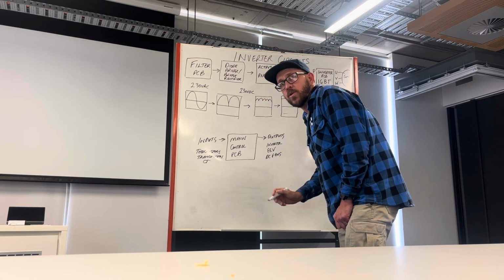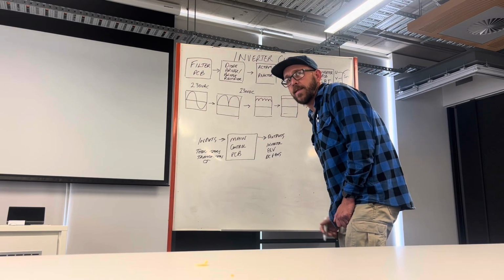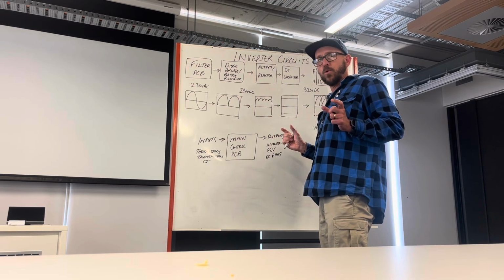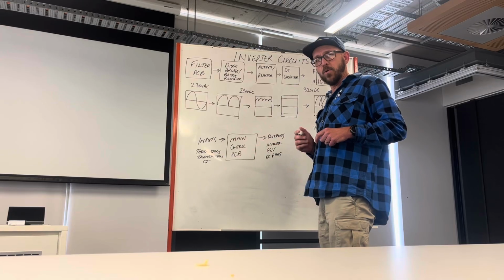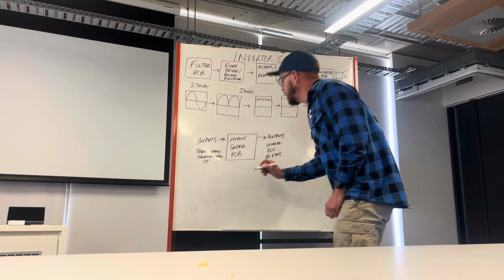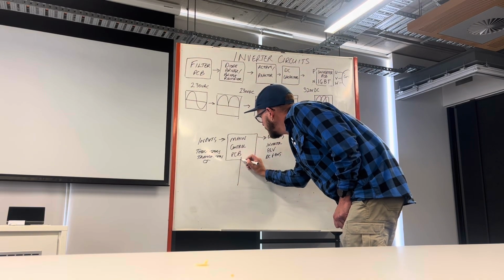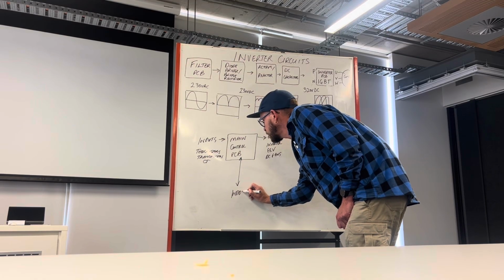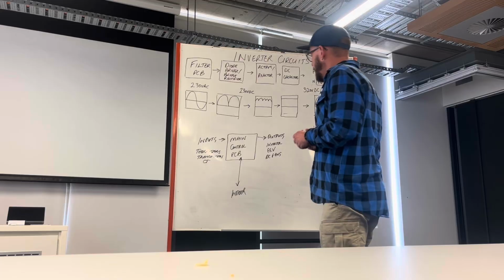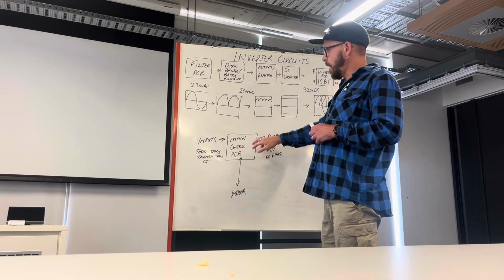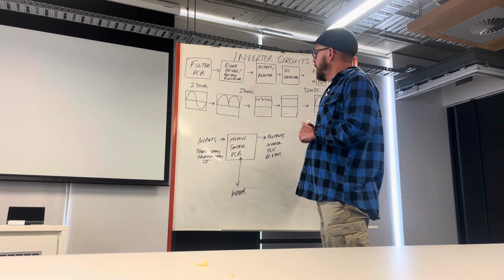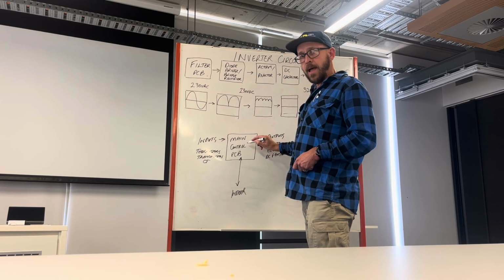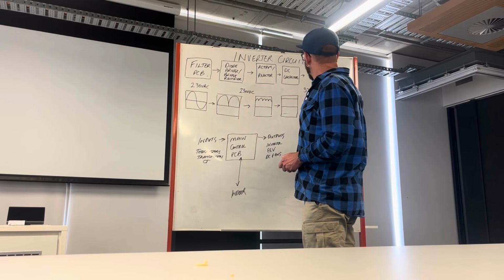The main control board does the communication between the indoor and outdoor. Both indoor and outdoor will have a comms board or a main board that's dealing with that communication in both directions to the indoor. Now, this main board only works if it has got AC voltage coming into it and also DC voltage.